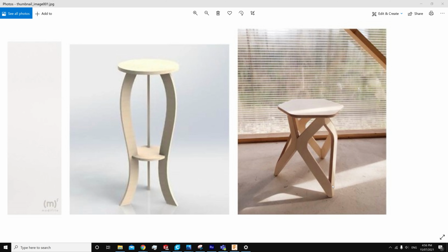If I was going to do this on a CNC machine, I would probably cut them purely 2D and then actually get that angle perfect on, say, a table saw manually, because it can be a little bit tricky and time-consuming to set up that nice mitered joint for a small quantity run like this. If we look, this piece actually has essentially 3 sides, which means this angle here is going to be close to 120 degrees. So for that, you would probably buy a special 120 degree cutting tool, which wouldn't be something you'd invest in for a one-off, for example.